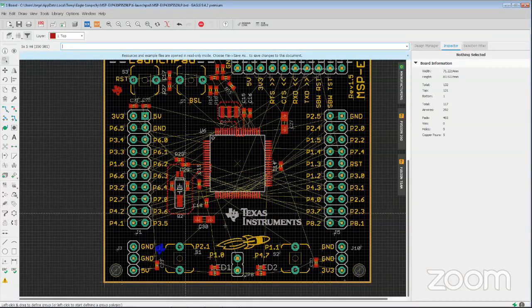So what you can do is route those careful traces and then let the autorouter finish the stuff that is trivial, the stuff where it's not critical how it's routed. And in that way, you save time. You're not fully manually routing the board. You're manually routing the important parts, and then you let the autorouter finish what's left. And that's a net time savings versus manually routing the whole board. So that's one way you can leverage it to save time.